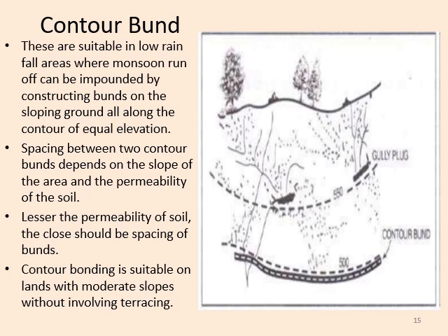So here the contour level is 500 meter maybe, and according to that contour line the bund is constructed. Spacing between two contour bunds depends on the slope of that area and the permeability of the soil.